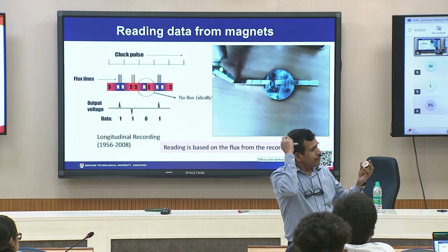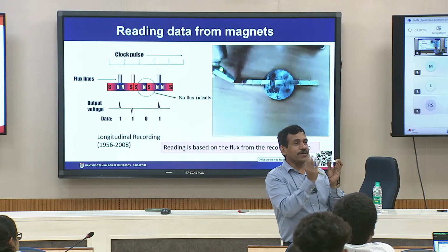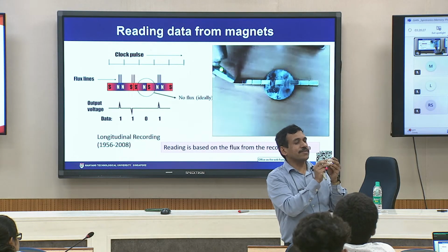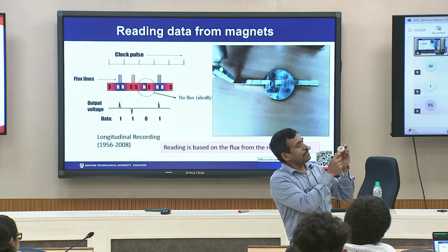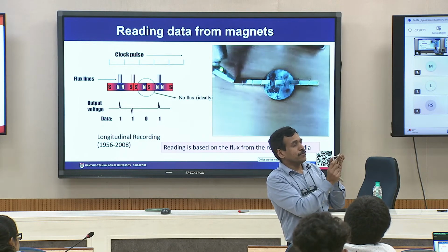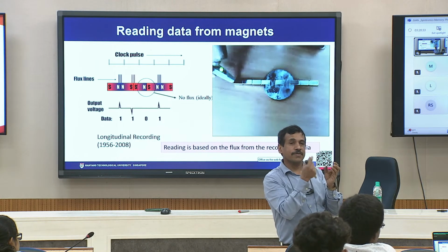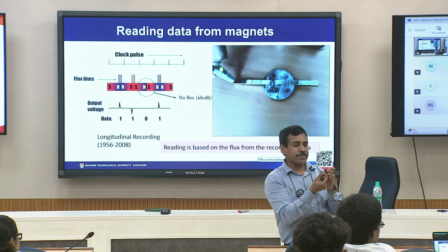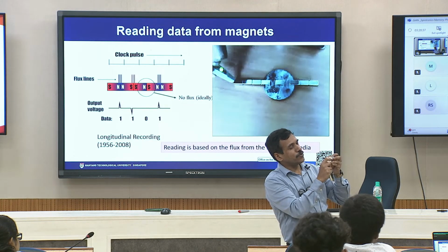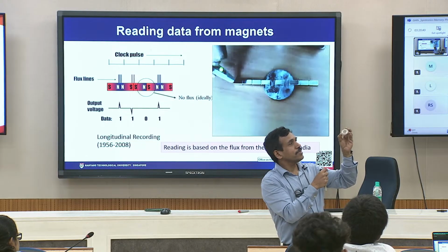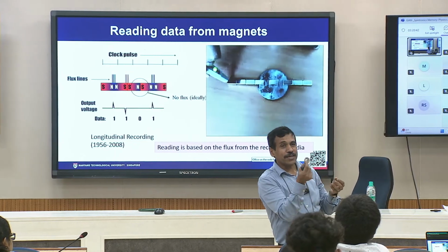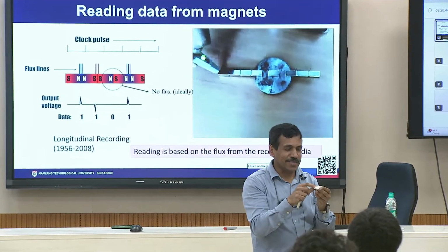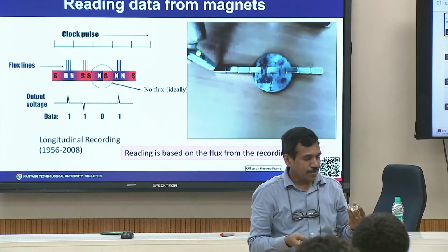Secondly, we learned about the target and magnets below the target. In this case I am showing you a target and the erosion profile. Here we have symmetric magnets. Because the magnets are symmetric, you can see a large portion of this target is eroded and we cannot use it anymore. So, that is one thing I want you to have a look at.